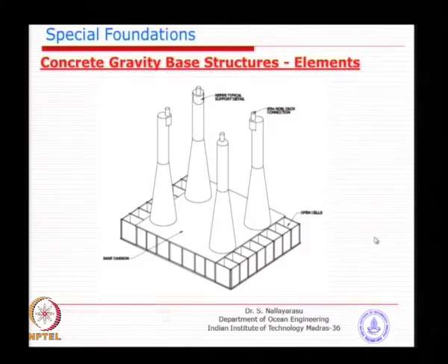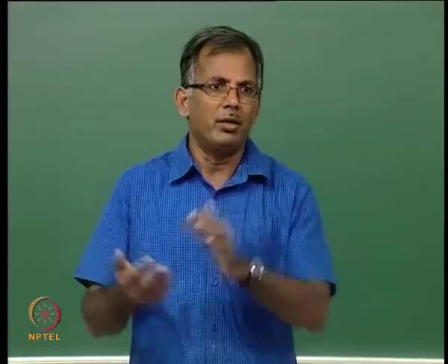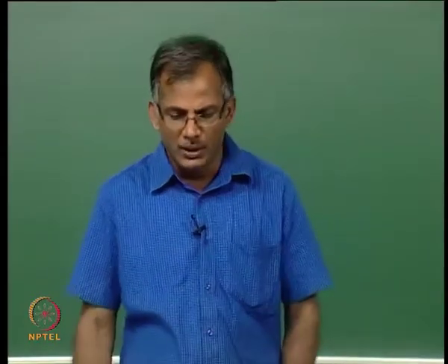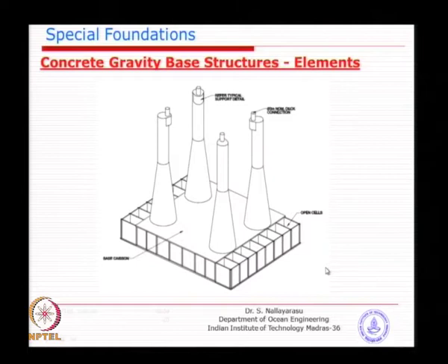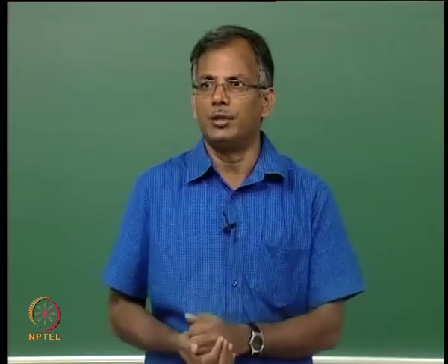A typical concrete based structure, you can see here, is rectangular cells, many of them assembled together. For us as foundation engineers, what is important is the interface between the structure and the ground. You can see it's a rectangular shape. When we want to construct or design a foundation, it is nothing different from a mud mat. What you have learned is exactly the same, because we don't have a skirt. The only difference is you have a large size structure instead of a smaller mud mat, and the material is concrete instead of steel. That is the change that you are looking at.